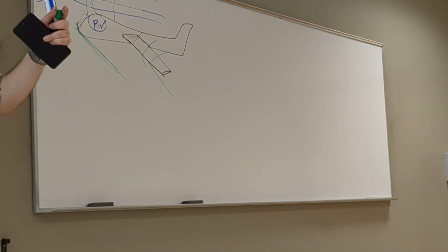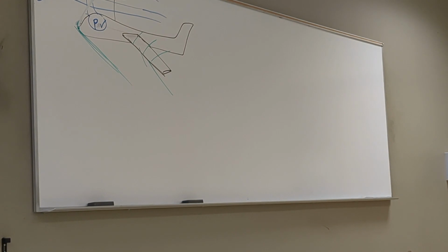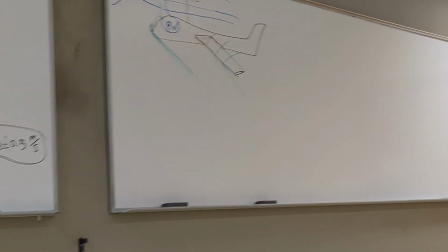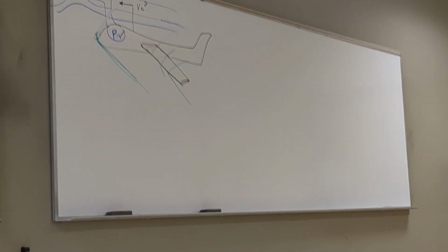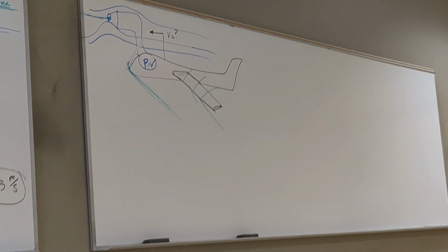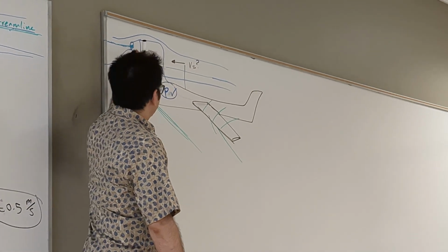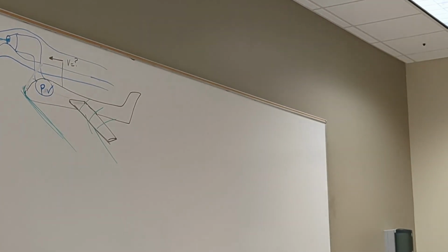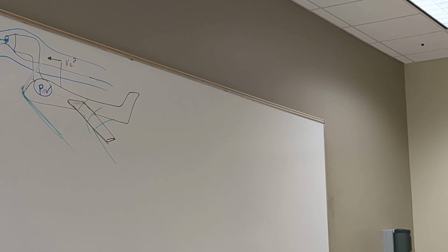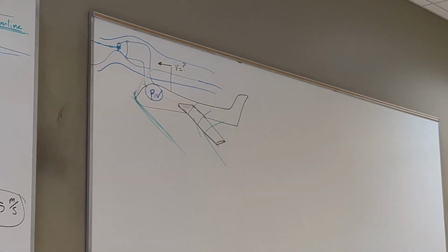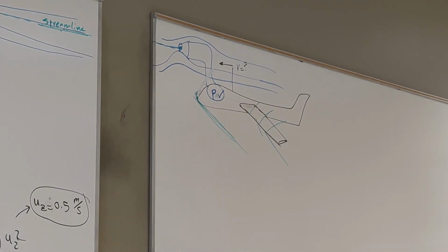So even if you go compressible, you get a number, right? And they have a calibrated form of the Bernoulli equation for compressible flow. So they designed this calibration between the pressure measured here and that, such that it also works in the compressible case, even if the density changes. That's a different equation, so they designed it based on that. But if you know this, you can do that too. It's not a big deal. It's just that you solve for a different type of equation, but the principle is the same.